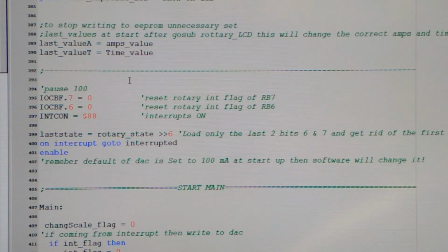So here's what I've seen with a lot of Arduino sketches. They don't bother to do that. Sometimes it just keeps writing to your EEPROM, even if you haven't changed the value. So, you know, if your door is closed, why go and open it and close it again? It's a matter of seeing whether it's closed or not. And if you want it closed and it's already closed, don't go and open it and reclose it, because every time you write something, that's sort of what you're doing.